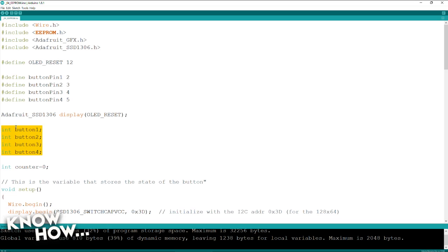Also, there are different amounts of memory. So this is really where you start looking at what type of Arduino do you get. So the Uno or the Nano, which are the ones that we've been using almost exclusively, they have 32K of flash, they have 2K of SRAM, and 1K of EEPROM. But the Mega, which is the next one up, has 64K of flash, it has 8K of system memory, and then I think it has 8K of EEPROM. So substantially more. Substantially more, right.